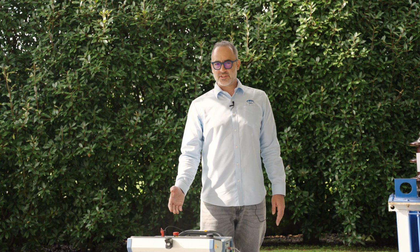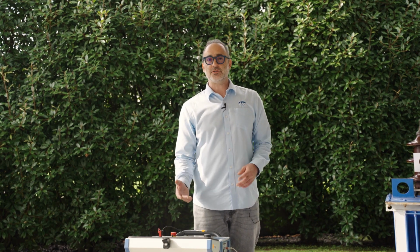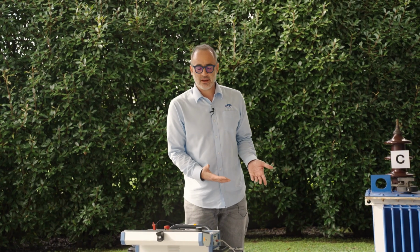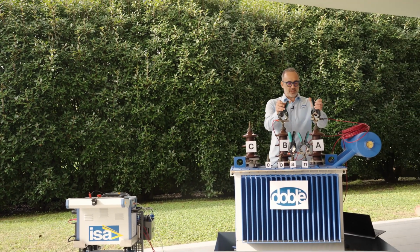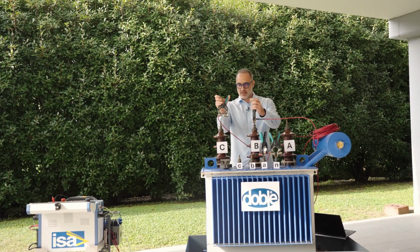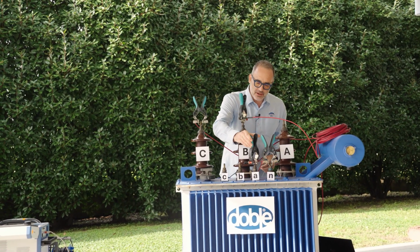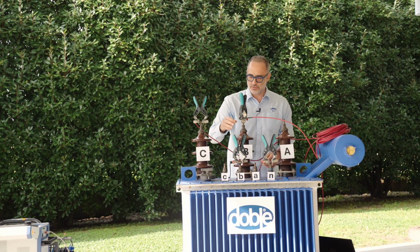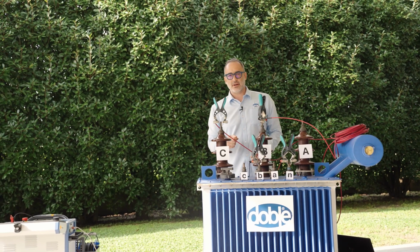So having done the first test on phase A and having obtained good results, we need to change the connections to phase B. So let's see how we do that. Very simple. So now I will be generating between phases B and C, and I will be measuring on the secondary side between phase B and neutral. Having connected like this, let us do the second test.